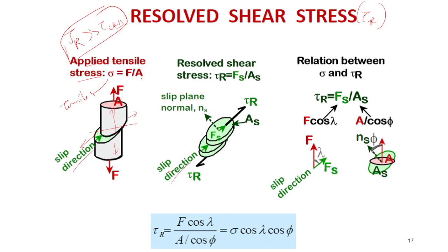Right? Sir, the slip direction will not be like this, as it will be forming a cone structure, sir, cup and cone structure. Oh, yeah. So why are we considering only a slice? Oh, no, see, actually this is in terms of a single crystal. A cup and cone structure usually forms, I believe, in a metal, that too a polycrystalline structure, right? So this is a single crystal. Usually, when deformation happens in a single crystal, it will be in this 45-degree direction.